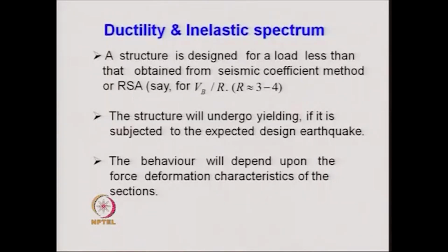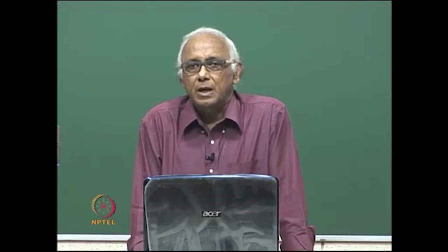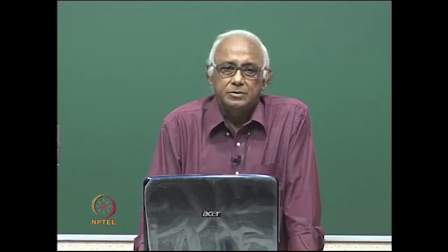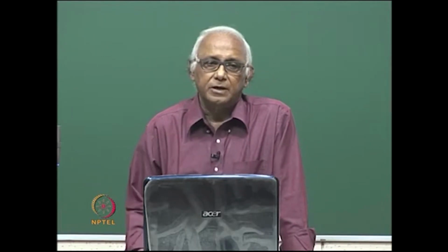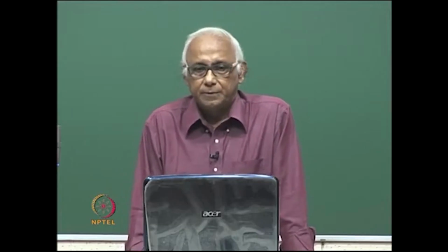After that, we discussed a very important topic called the pushover analysis in earthquake engineering. The pushover analysis is a very good equivalent static nonlinear analysis of structures for earthquake. With the help of pushover analysis, we try to understand the inelastic behavior of the structure after the yielding during the earthquake, and also try to see the performance levels of the structure at different stages of the earthquake loading.